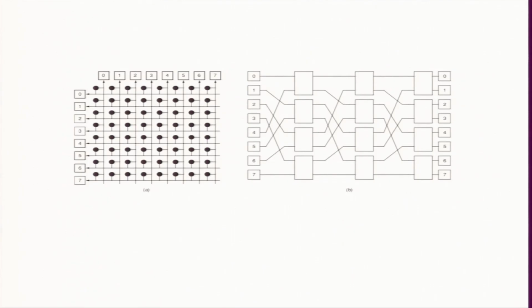Now, let us quickly look at one more architecture. The crossbar I discussed has many links. For simple connections, there is the Omega connection. It has fewer wires, but you cannot reach anywhere to anywhere in one hop. The crossbar requires only one hop, anywhere to anywhere. Here, let us say I want to go from 0 to 6, then what will I do? I have to go there, and from this side I need to go there. So, I need to use this branch and come here.